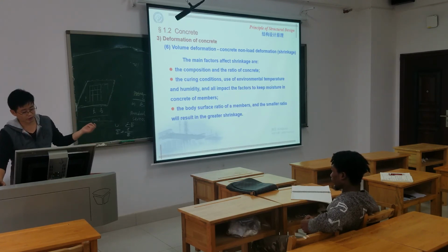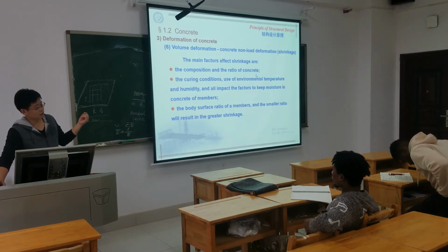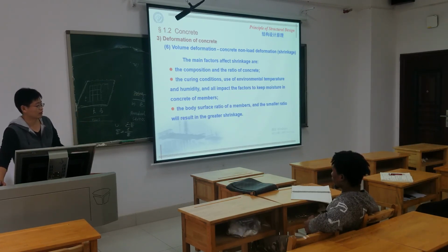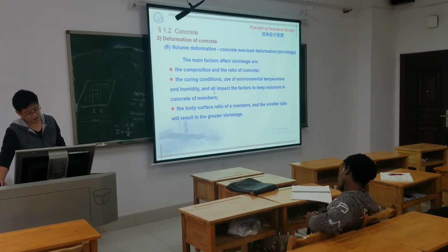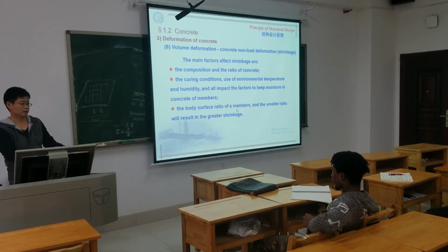So if the ratio of the concrete has a large amount of water, then the shrinkage may be large. So the curing conditions, the environmental temperature, the humidity, all impact the effect of keeping moisture in the concrete of the member. And the volume-surface ratio, yes, the volume-surface ratio.